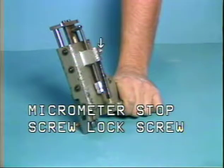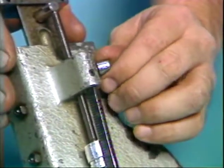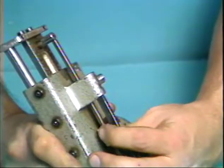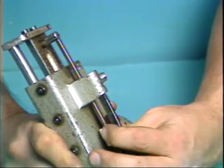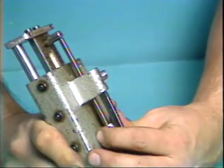This is a micrometer screw lock screw. The lock screw must be loosened to adjust the micrometer screw. Turning the lock screw counterclockwise will unlock the stop screw. Before mounting the 1-to-1 attachment, the approximate feed length should be set. Use the same procedure as used on the 2-to-1 attachment.